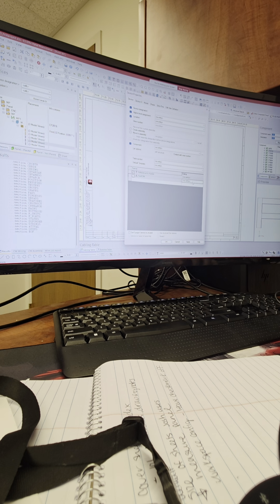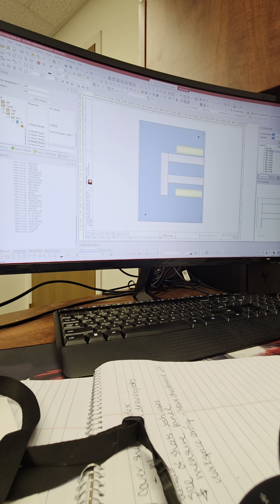So I usually put in 1 just to have some content. But I think even just the sheer presence of the no BOM attribute is sufficient. I probably should confirm that just to make sure that is correct. But I think just having the attribute should be good enough. So adding this 1 is kind of going above and beyond. It's really needed or not needed. But the no BOM is what excludes these items from being on your BOM and on your reports, as in they don't exist. Okay, if you click OK, that will do that part.